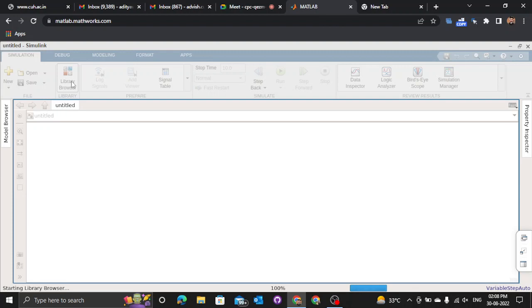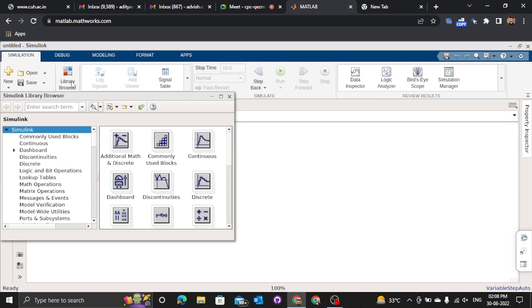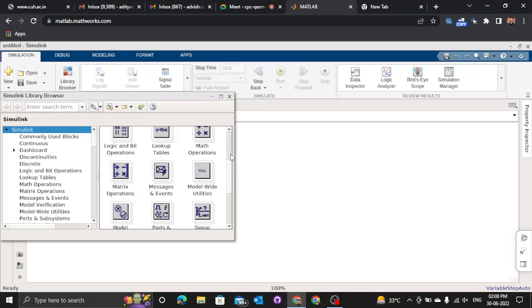This is the pulse generator. Okay. So you can connect this pulse generator to this. If we are giving the signal to this triac, you have to connect an AC voltage supply source here, and we need to connect a load, that is resistance. For taking the resistance, we have to take the series RLC branch again, as we have done in the previous experiments. We can say 100 ohm resistance we can take, and make L and C as 0.